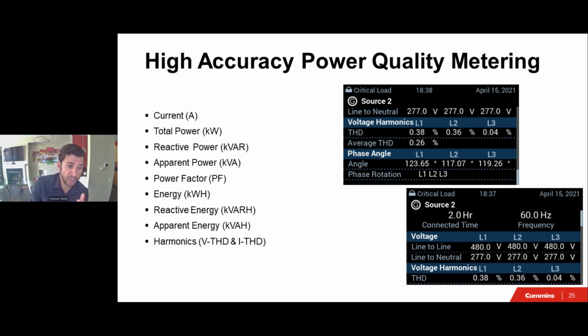Well, maybe we have a total harmonic distortion both on the voltage and the current. And we probably want to have, if the percentages are in the higher percent, 3-4%, well, we have a problem in here. And this transfer switch control can tell us or alert the operator, hey, you may want to investigate your load. There's a problem in here. I mean, if you're less than 1%, you're at 0.5%, so that's pretty healthy.